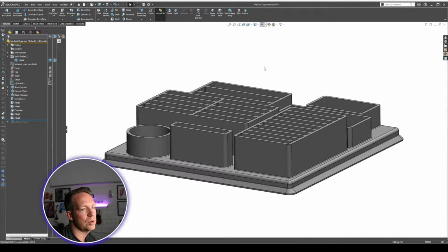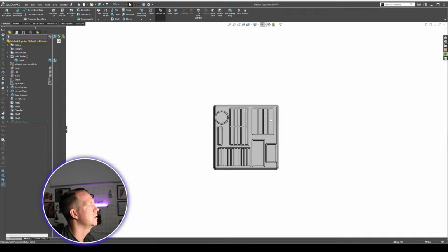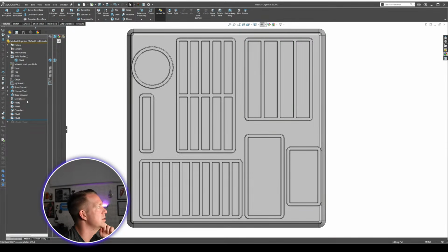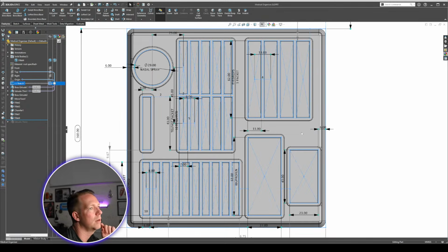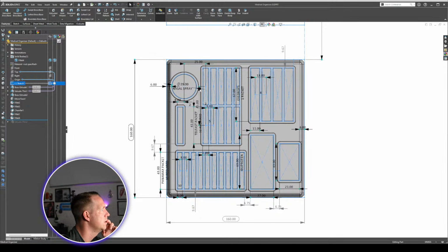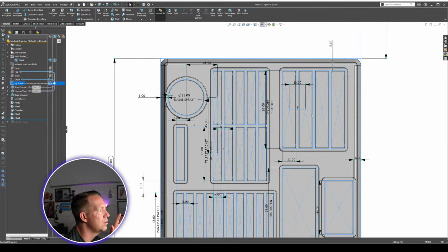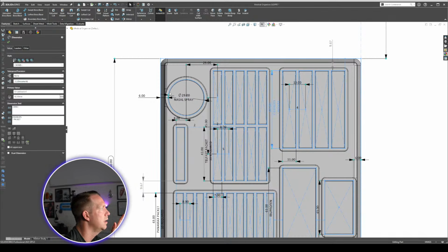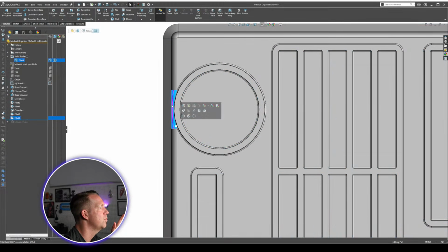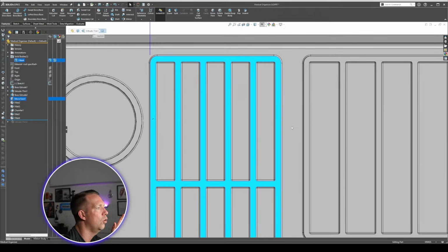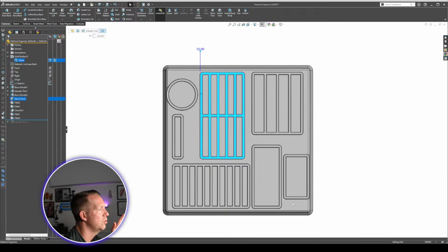So this is where it is really handy to be looking at, again, your driving sketch. And that's what we've created here with sketch 1. Right, we come all the way back to the early sketch. And now we can start to adjust again and say, hey, what do we want to move to get a little bit of clearance here so I don't have this weird fillet? I have to move this circle back. This gap is a bit small. I've got all this room here. I don't have much room here, but this has room at the front. So you can see where you can start to make different judgments about how you're going to do it.